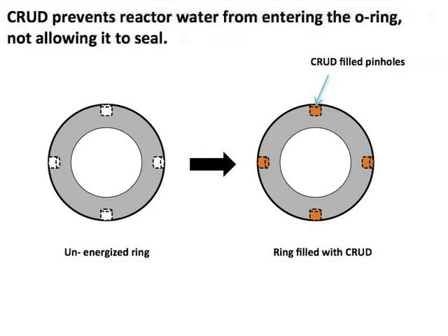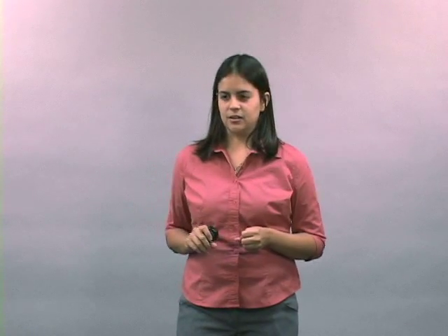Also, these O-rings are installed with heavy lifting equipment, which leaves a lot of room for human error. That means that if there's a slight mispositioning in the installment, that could either defect the entire O-ring or even just break the Teflon coating, and that would cause it to be less durable to the thermal cycle, which I will explain later. Now, what are the consequences of these things happening? Well, according to Declan Doran, a qualified nuclear engineer at the plant, a hot rod, as it is called, or a heated control rod, will move slower into the core than a normal control rod would.